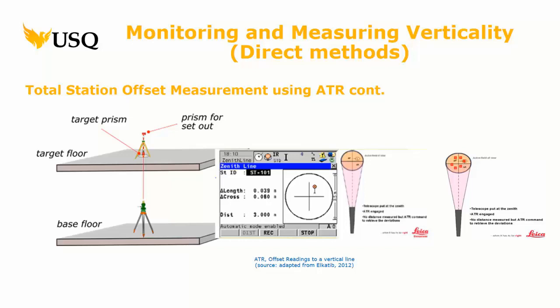So what actually happens, and this is just a review aspect, is that you have an image of the target taken by the total station, right? And it compares the image of the target to where the crosshairs are. It's all mathematical. And says there's a delta X and a delta Y. That converts to minus 1.3 seconds in vertical and plus 2 seconds in horizontal. And it applies that correction to your angles and distances, right? Both vertical, horizontal, angles and distances. So you go to another target, it might be totally different because the image might be different. So it changes all the time.